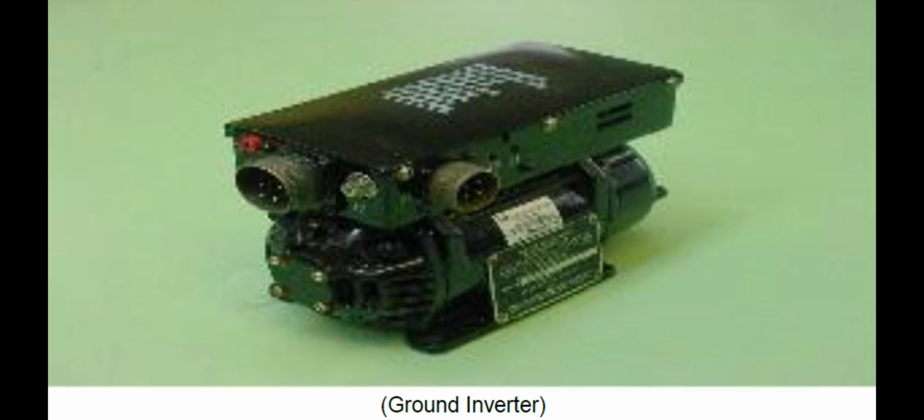Under-frequency microswitch. An under-frequency microswitch is mounted on both the left and right main landing gear. In the air, the switch contacts are closed, providing a path to ground for the air-ground relay. This is for the under-frequency portion of the supervisory and voltage regulator panels, the HRS, weather radar, and auto reignition.